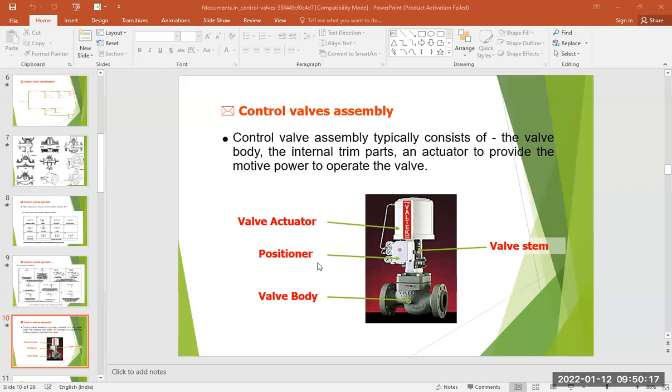And another one is the digital. Okay, so this digital input type of positioner system basically has the same function as the analog input, and also works with pneumatic type actuators. Here we use the 0 and 1 concept also. Here 1 is the on condition and 0 is the off condition. And here we have to attach a digital communicating system in these systems also. Okay, that is, transmitter and receiver circuits we have to attach in this digital positioner control system. So these are basically the positioner systems.